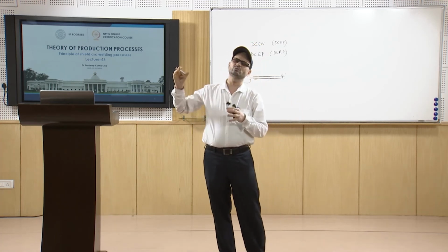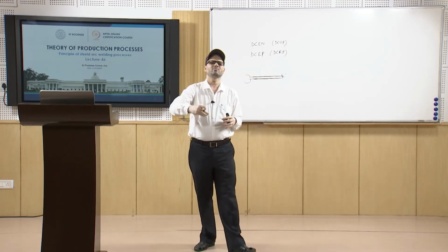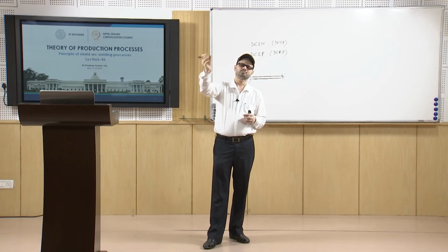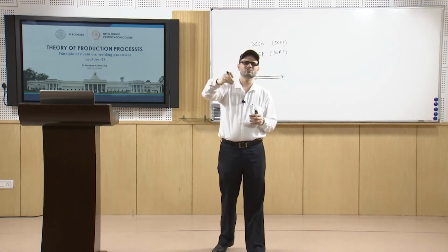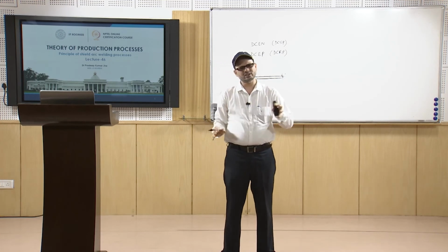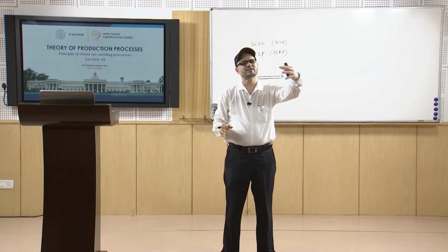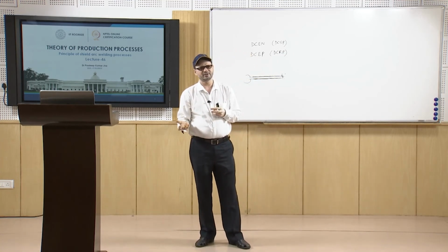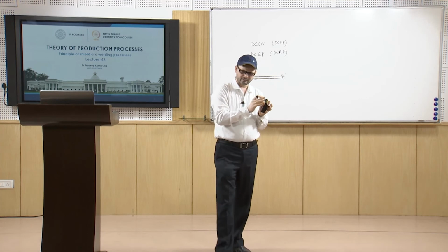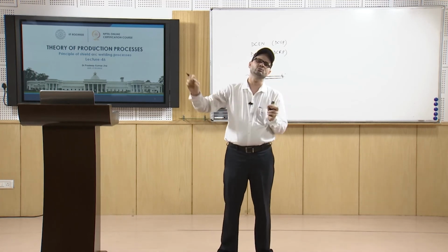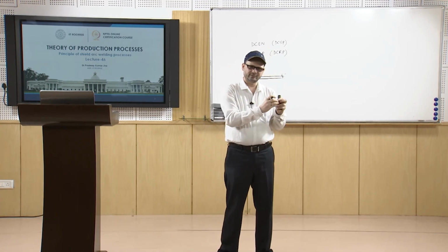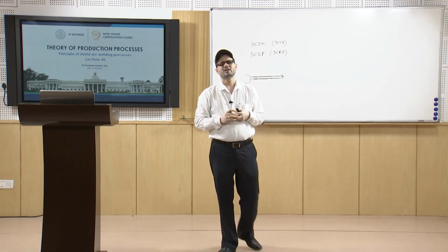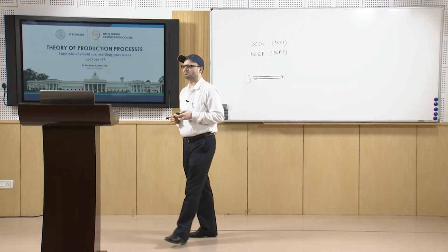Since it is in the form of bare wires, they come through a mechanism by which you can continuously feed the wire. There is basically a challenge in the case of shielded metal arc welding that does not remain here. In this case, the arc can continue for long, and that way very large welds are possible in submerged arc welding.